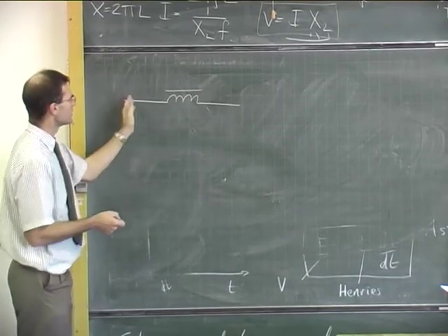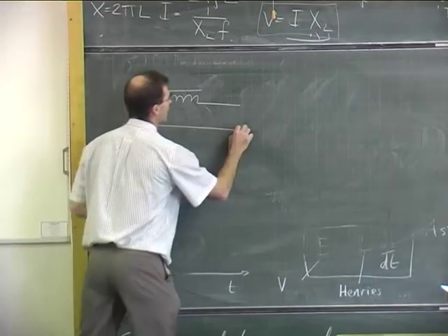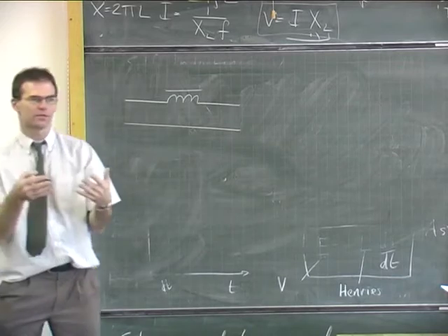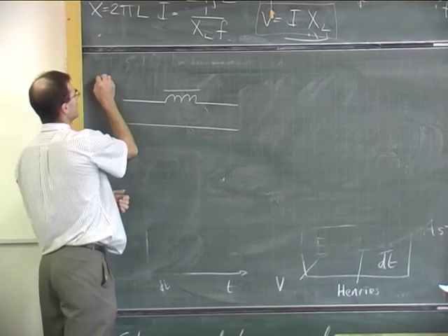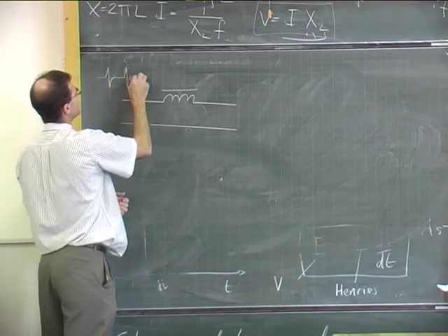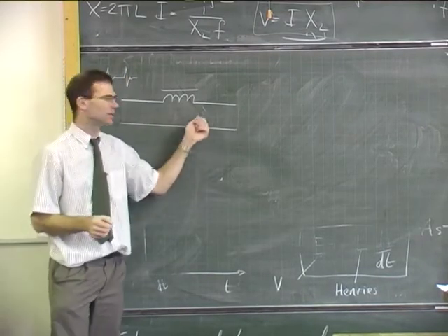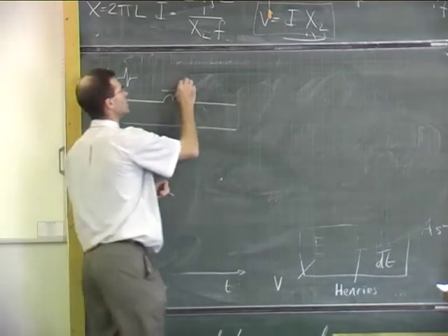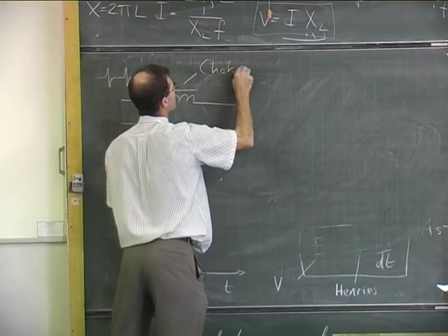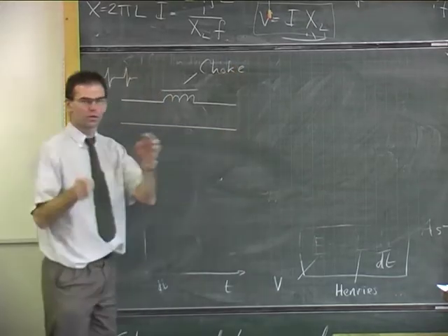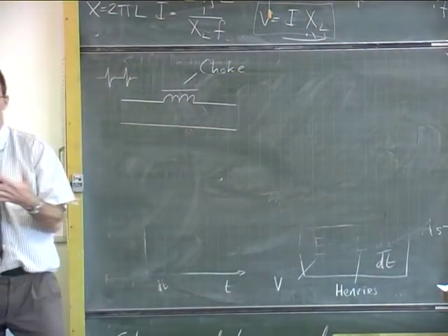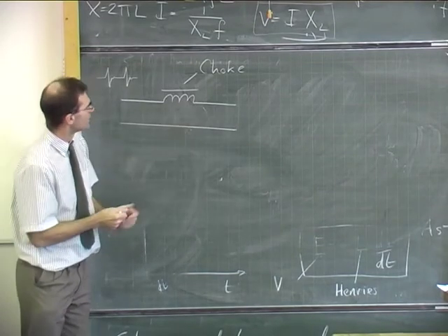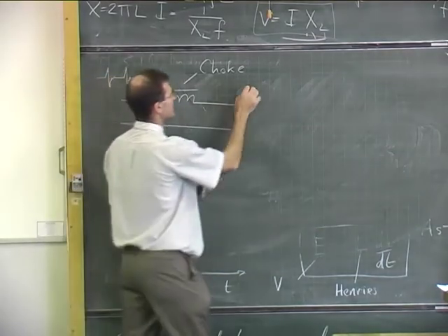So if you've got something connected up and you want a pure DC, say it's a bit of electronic equipment, and you want to prevent in your DC any spikes in the line due to interference, there's an inductor, and in automotive electronics, we would actually call that a choke. So you might sometimes hear a coil of wire in series with say a car stereo referred to as a choke, because it chokes off the AC in the circuit, and you end up with a much cleaner DC.